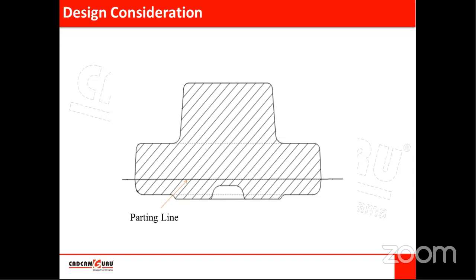These are connected by bushes or bolts. Here we need this for power transmission. That's why definitely they should be manufactured by the forging process, because strength is required as a basic parameter. So we are manufacturing this by the forging process.